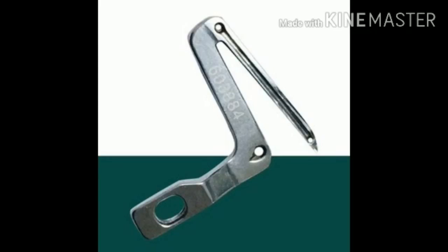One of the most common types of failures experienced and observed in the machine is the upper thread breakage, and there are various reasons why this happens. One of them is wrong threading of the machine, poor quality of thread, irregular tension. These were some of the reasons why upper thread breaks. If we discuss why lower thread breaks, it also has a few reasons. One of the main ones is wrong threading of the machine, poor quality of thread, irregular tension, inferior thread or mismatched thread. Bobbin case is too tight, needle plate hole has sharp edges or shuttle has a rough spot.